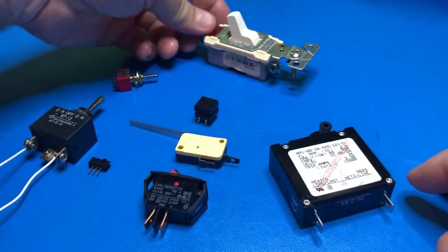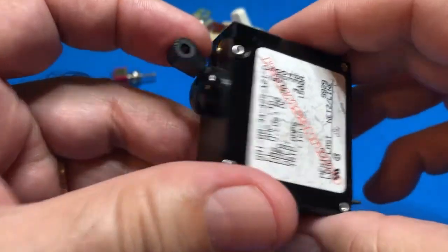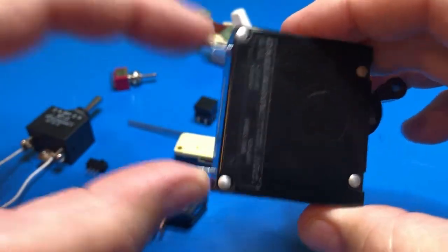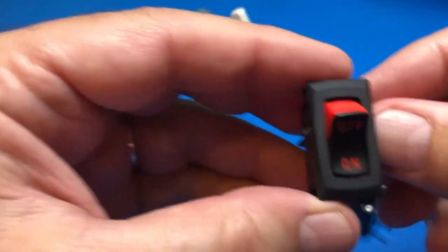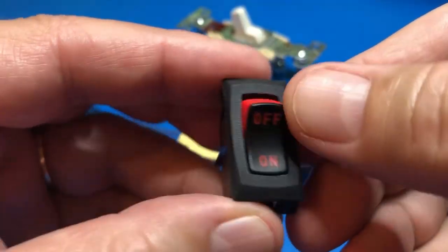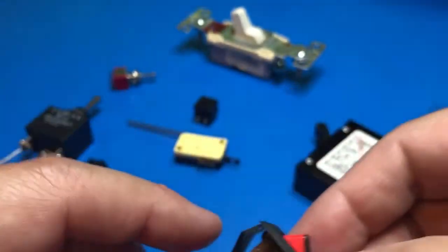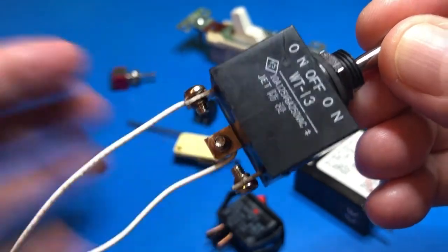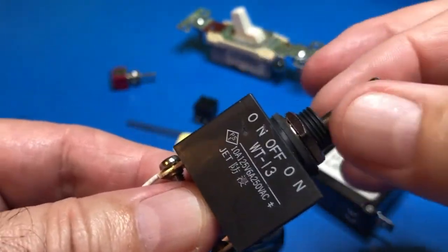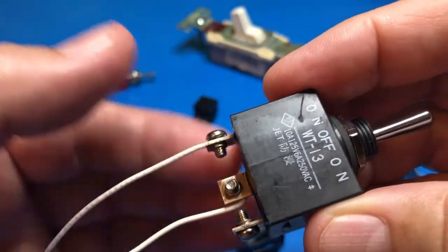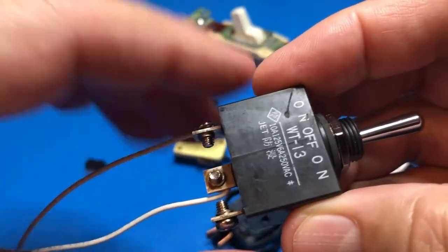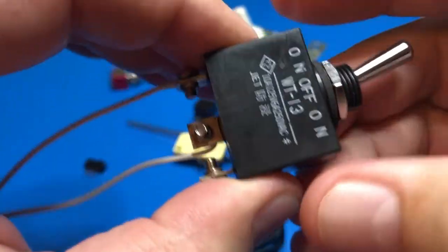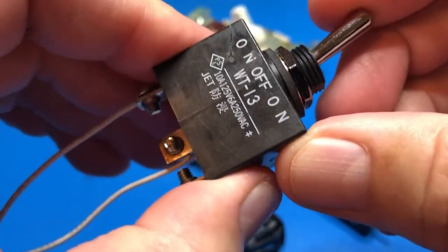A similar type of this switch that you may find on pieces of equipment like computers is this one. You get the lever there and the contacts. Similar type. Even this one shows you which position is on or off, and here are the contacts. Similar, but this one has 3 contacts. So what happens here? When this lever is in the center position, there is no connection, no contacts connected to each other. When I move this way, these 2 get connected. When I move the other way, these other 2 get connected.